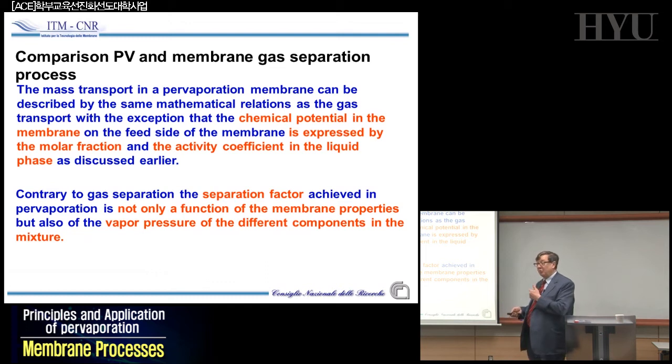Because the separation normally was that if it's true that the vapor phase is enriched in the more volatile component, you make the separation, you condense your gas phase, and you have a liquid phase enriched in the more volatile component. And if you do this kind of operation 100 times, 1,000 times in the different plates of your distillation tower, you will separate the components of your feed solution.